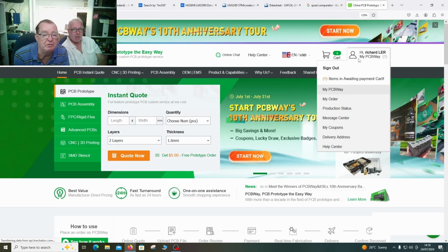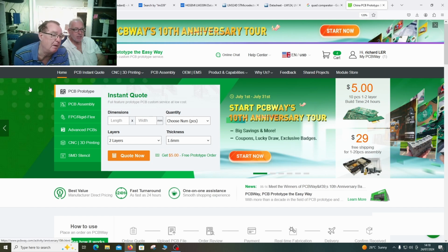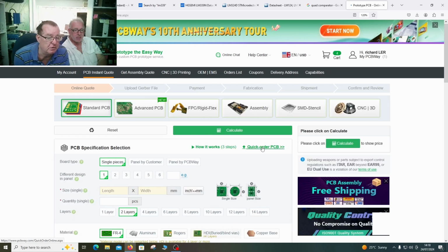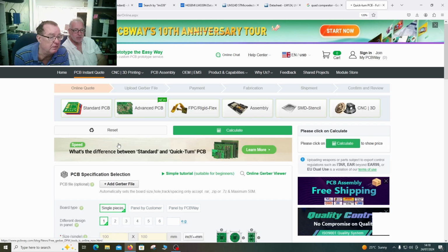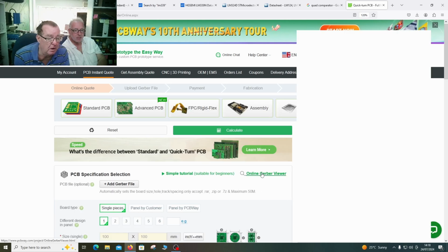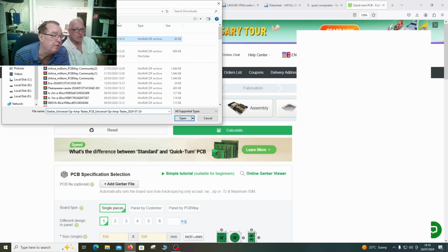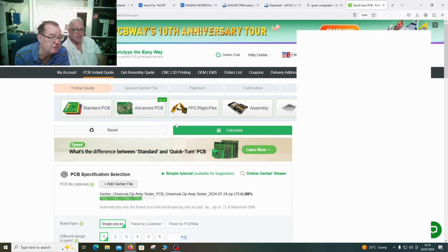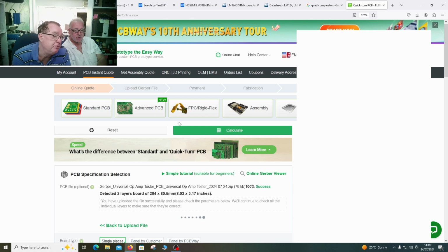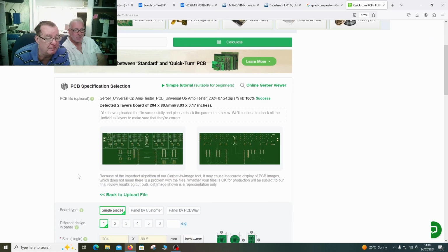Okay, so I'm logged in on my account. We're now at PCBWay.com. Let's order our PCBs. So we go to PCB Instant Quote. We go to Quick Order PCB. And we go to Add Gerber File. So this is the Gerber file produced by our design software. And you can use any PCB design software you prefer to do this. We now have our board. You can see the board there.